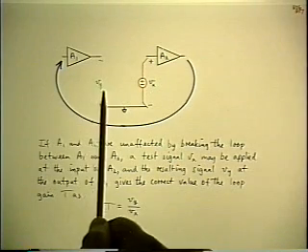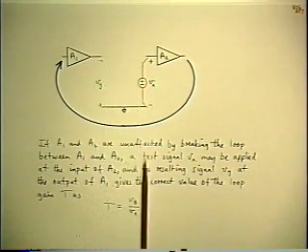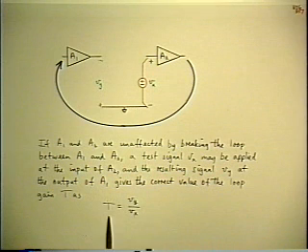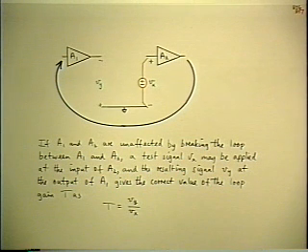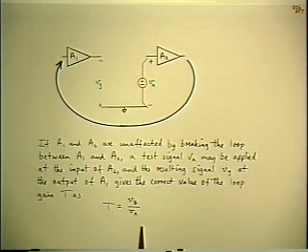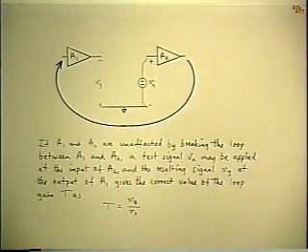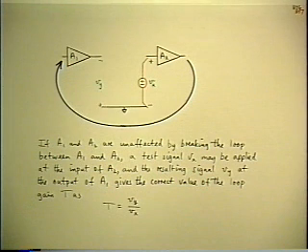That polarity relationship is necessary to ensure negative feedback. So what I've done in the picture is define Vy as minus so that Vy over Vx, which is T, is a positive quantity. And that's consistent with its use in the equations that we've had so far, where the denominator is 1 plus T, and T has to be positive. So this is the reason for defining the Vx and the Vy with those polarities.